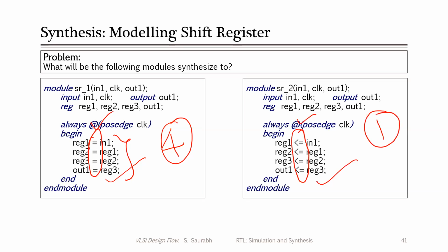Any other participants want to comment on this? Sir, first one would be a shift register, maybe. So here you will have 4, right? Yes, 4 flip-flops, serial in, serial out. Okay. And in this case? And in the second, parallel in, parallel out.